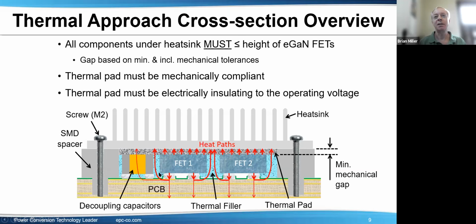Basically the top 90+% of the GaN FET is inert silicon wafer. It just kind of sits there. It's like a holder for the GaN layer. The GaN layer is a thin layer that exists right here. So the current comes into the bottom and leaves from the bottom, and the heat is generated more or less evenly. There are thermal diagrams and a thermal model for each FET, but it's kind of evenly throughout the FET here on the surface.